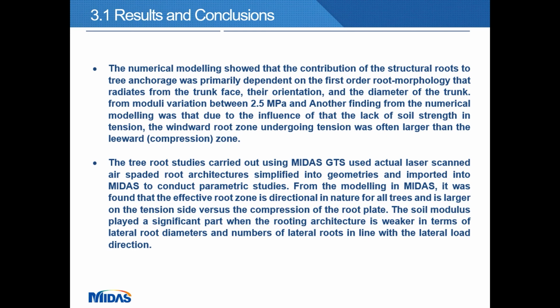We found that the numerical model agreed with the tests that we did in place. So we understand the influence of the lack of soil strength in tension: the windward root zone undergoing tension was often larger than the leeward zone. In the leeward zone, we will experience compression, and in the windward zone, we will experience tension.